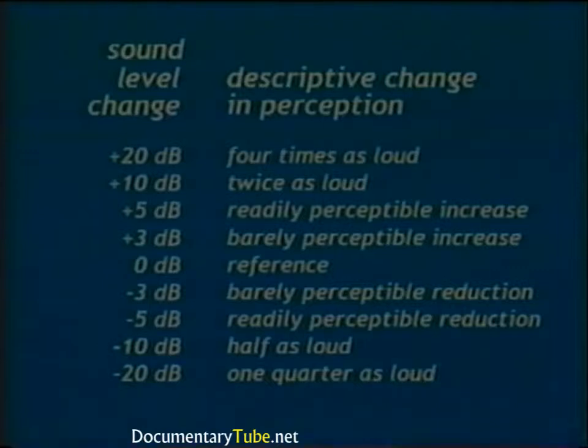When the sound pressure level increases or decreases, some humans in a normal living environment can detect a loudness change if the sound pressure level is altered by 3 dB or more. A change of 1 or 2 decibels will usually go unnoticed. A 5 dB change, on the other hand, can easily be detected by most people. Also, sound will be perceived as being twice as loud if the decibel level increases by 10 dB, or will be half as loud if decreased by 10 dB. And it's common to perceive a 20 decibel change as 4 times as loud or 1/4 as loud.